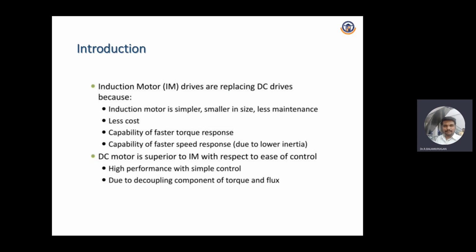The induction motor is simpler, smaller in size, and also has less maintenance, less cost, and capability of faster response compared to that of the DC drives. The speed response is also good compared to DC drives. But we will also go for DC motor drives. In DC motor drives, the first major advantage is ease of control, and performance will be high compared to that of induction motor drives.